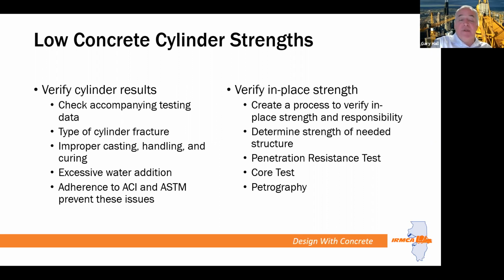And if the cylinders fall within that, then we can assess that the strength is correct. Other in-place strengths, if we've exhausted that, we can do penetration resistance or coring to determine if the in situ strength of the concrete is in fact okay. Then we could resort to petrography as well to look for root causes of concrete failures.